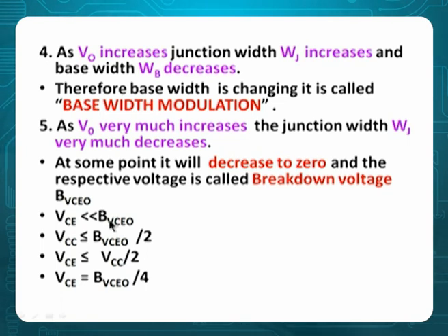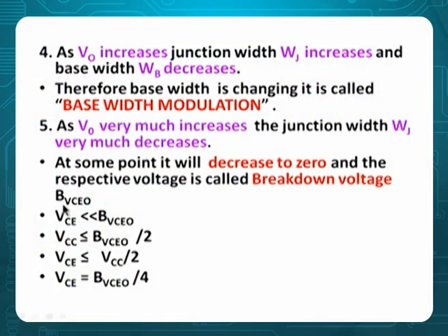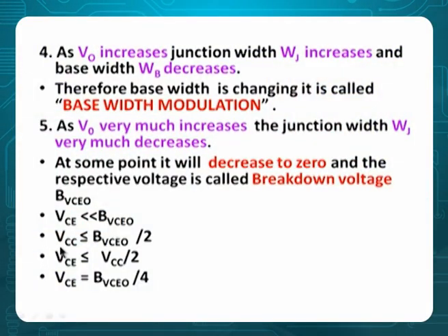You have to use voltage very much lesser than breakdown. That's called actually breakdown voltage. Breakdown voltage is the voltage at which punch through occurs. Punch through means base width becomes 0. So what to do is, take lesser than that. VCC, take half of BVCEO. And generally VC is half of VCC by 2. Therefore, the voltage that you are taking is almost 1/4 of the breakdown.